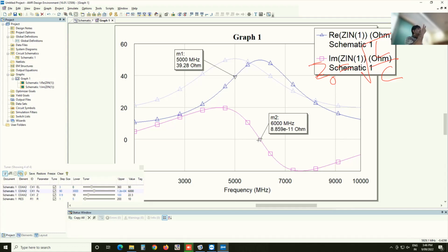So you need basically two things to define your impedance transformer. One is the effective length. It has to be a quarter wavelength at the frequency which you're interested in. And then you need it to have the right characteristic impedance. So that number does not depend on the frequency. Okay. So just to maybe show you that formula, and I think we should wrap up in a few minutes.